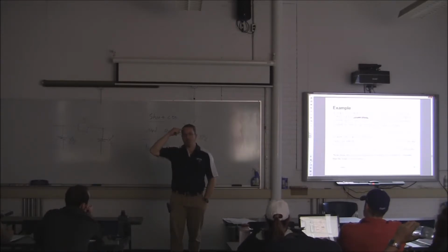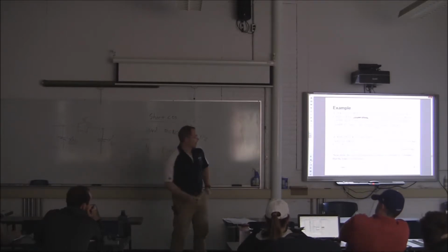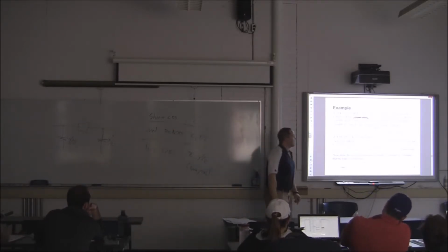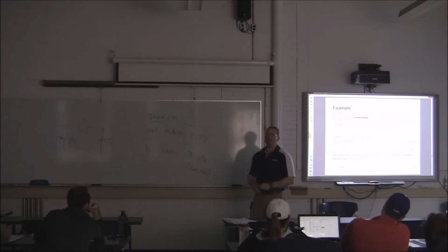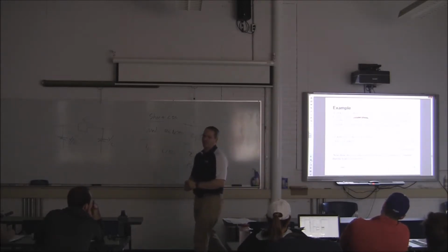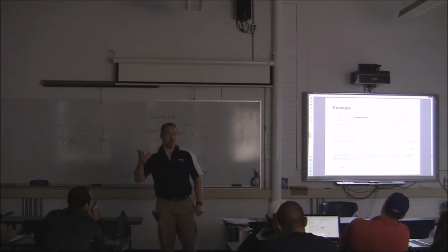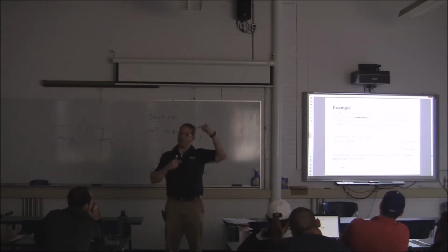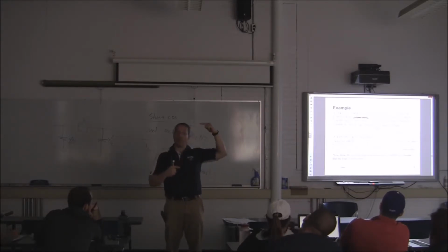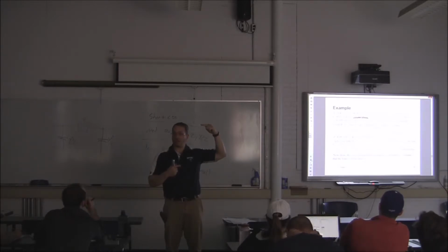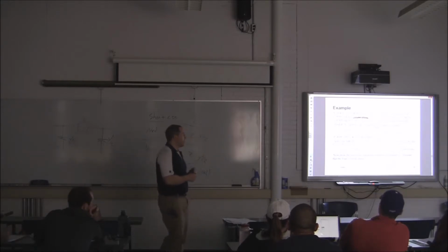So what voltages and currents should I be using in my analysis? Single phase quantities. Is 345 kV a single phase or a three-phase quantity? It is a line-to-line quantity, right? So it's effectively looking at voltages across two lines. So the very first thing you need to do is divide that voltage by the square root of 3. Okay? Muy importante.